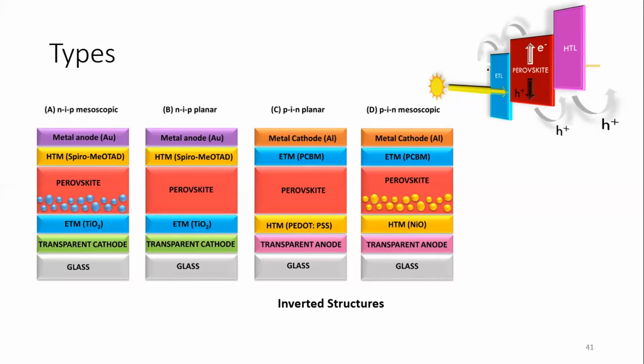This will further transport the electron to the contact electrode. Similarly, this hole transport material will efficiently separate holes from the absorber layer. In this way you can separate charge carriers and then send them to external electrodes, to apply them to some kind of load.